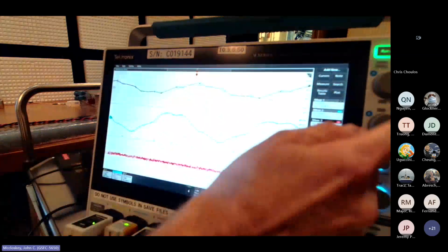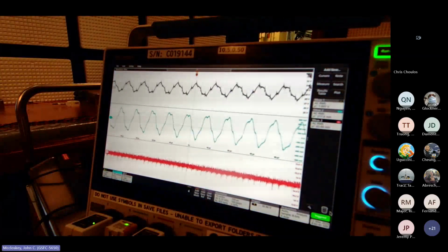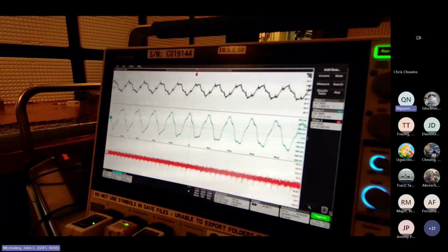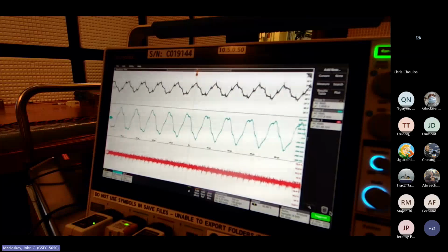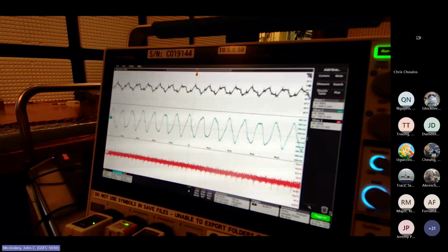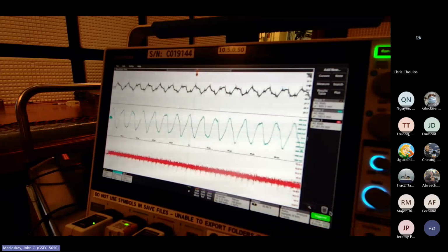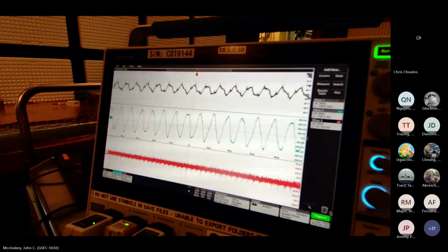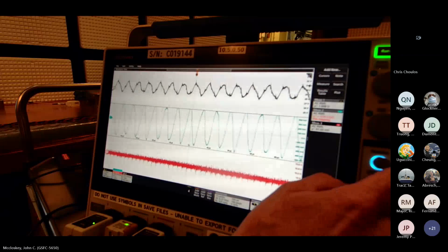So if we finish this up at 150 kilohertz, I'm just going to go to 150 kilohertz because I think the impedance goes up and signal level's going down a little bit. So I'll keep it with that right there. So we need to increase the amplitude just a little bit. Maybe a dB or 2 or 3. There we go. That's good.